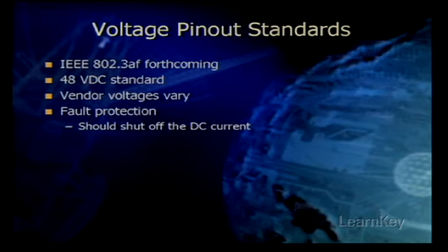Fault protection circuit operation will vary from model to model on different devices, so be aware of how your particular chosen vendor uses this voltage. Some models will continuously monitor the cable and will restore power automatically once the fault is removed. However, some models may not do this at all and may have to be manually reset or rebooted before they'll begin to process data once again, or even to enable that particular port. The same thing is going to hold true with just about any device that you plug in to a PoE port.